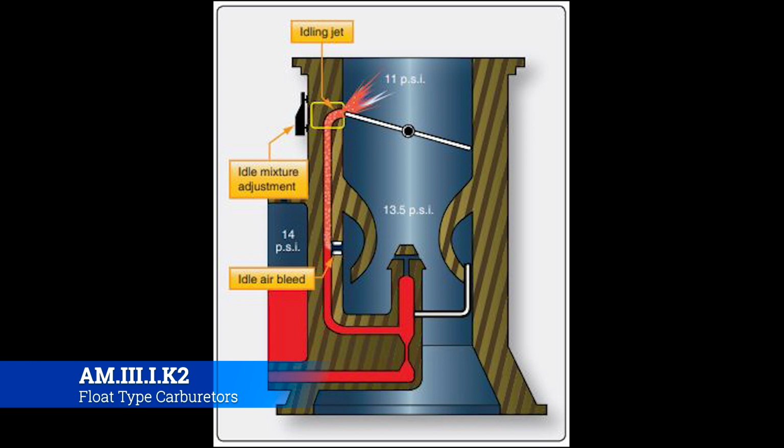Now, if you have an engine that doesn't want to idle, idle's really rough, this is probably going to be where your problem is. A lot of times you get some trash in there, or if it's set up for a long time, the fuel, which has additives in it, if you remember from General, those additives over time will settle to the bottom. Well, that's true in a fuel tank. You'll see the sludge on the bottom of the fuel tank. You have to kind of clean it out.